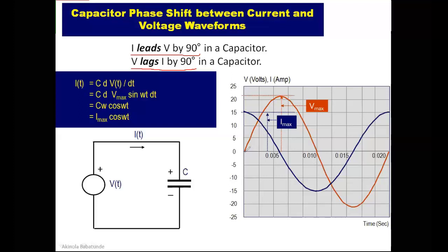This entire waveform you're looking at here, the full circle, is from this point to this point, and that full circle is 360 degrees when you consider angle. So this is half of the circle here. This is usually referred to as pi, and this is usually referred to as 2 pi, 360 degrees, because pi is 180. So this is a voltage waveform.